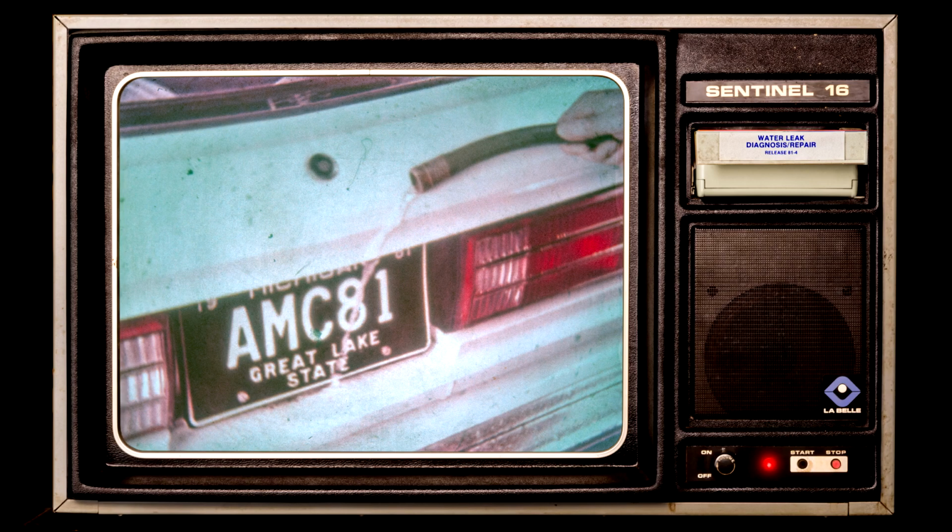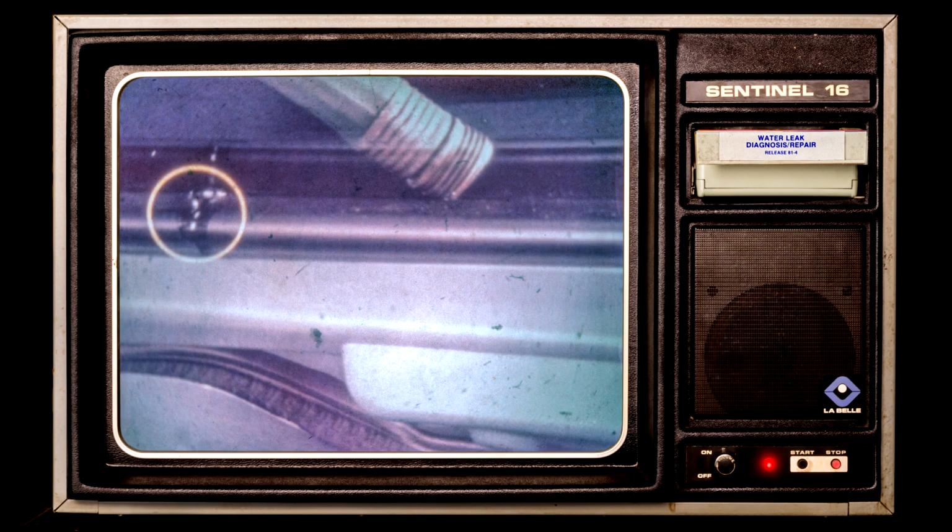If you don't have a listener tool, or if you perform an ultrasonic test that yields no clues, a water test is the next step. Notice that we're starting at the bottom of the leak area. The water leaking in between the rubber channel and the rear glass during this step reveals the leak location. This is a sealable leak. So now we need to prepare the leak area and choose the proper sealant.